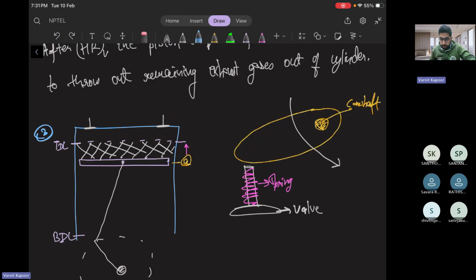Right. Volumetric efficiency plays a very important role for power generation, because you want a stoichiometric amount of the fuel, a perfect stoichiometric combination all the time. But in the real world, it cannot happen all the time. But you want the required actual amount of air fuel mixture to get sucked inside the cylinder, so that an adequate amount of power can be generated from the engine. That is why, if you have heard of the VTEC technology by Honda, I think it came back in 2000, initial year 2001.